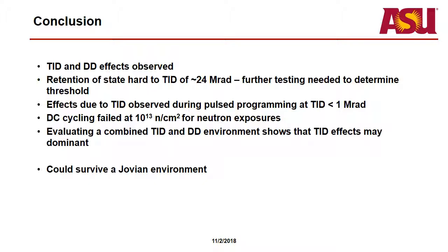And then for retention of state tests, we went up to about 24 megarad. And we didn't see any kind of abrupt failures like we did in a combined TID and displacement damage environment with the heavy ions. So if we want to firmly state whether or not TID by itself can have an effect on these DC type tests, then we would need to go to higher doses of radiation to see if that's relevant. Unfortunately, I was not able to get to those doses during my work.